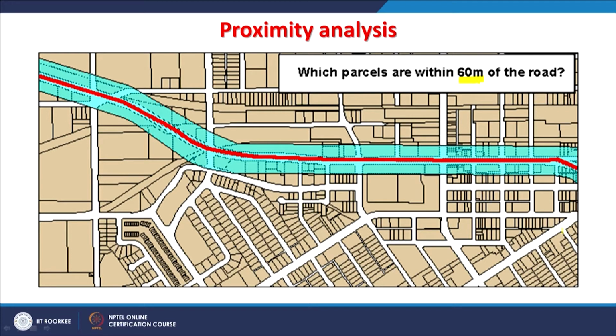Similarly, you can do analysis like if a stream is flowing, and I want to calculate the flood plain area. If there is a flood, say the maximum flood, and generally hydrologists use the 100 year time period, how much area would get inundated? That too can be analyzed using this proximity analysis. So, there are various such applications.